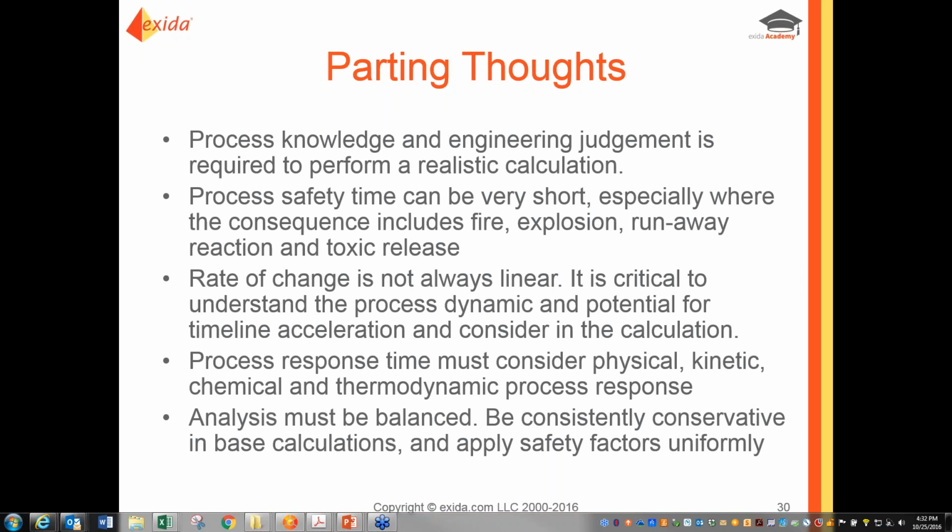However, you saw from the dynamics that I put together in these couple charts that that is not necessarily true, depending on the dynamics of your process. Sometimes your SIF response time needs to be much, much less than your process safety time because of the nature of things such as process lags or where the SIF set point is placed.